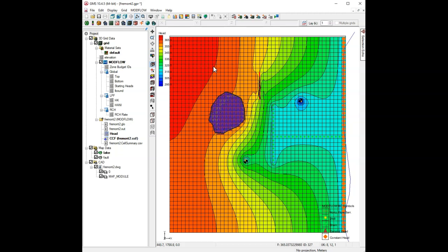And so when the water flows from the left to the right side, as we see here, this barrier should act as kind of like a little dam. It's not 100% impermeable, but it should cause water to back up. And sure enough, if you look on the left side of this, I'm moving my cursor there, we have about 355.8, almost 356 on the left, and on the right it drops down to 340, 338, 340, so there's about a 15-meter drop in water table as you go from one side to the other.